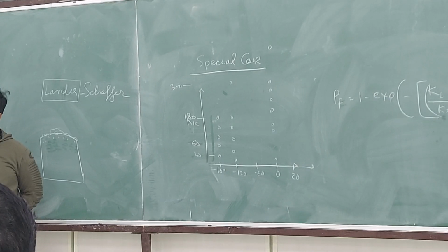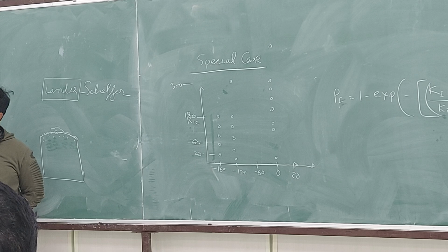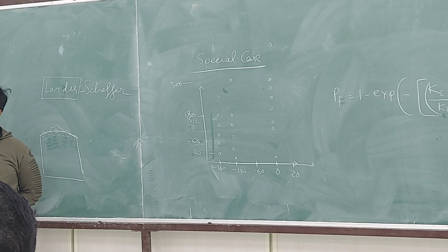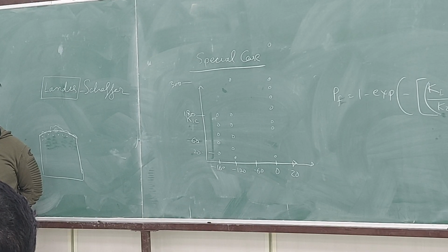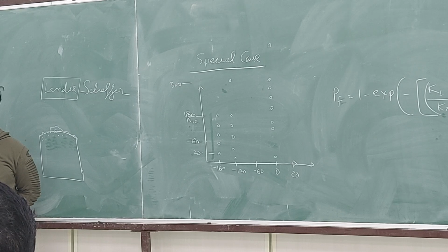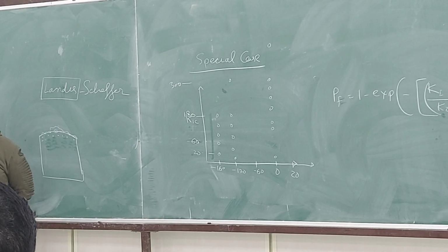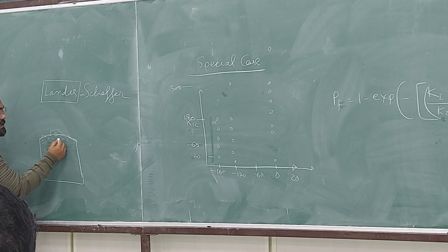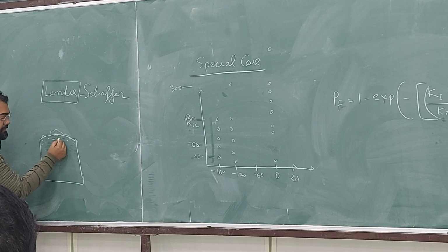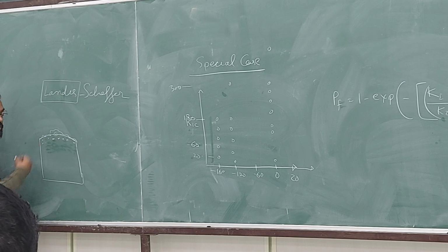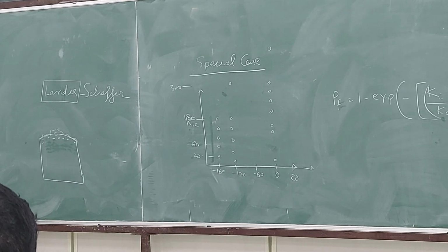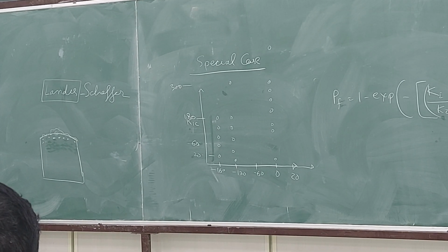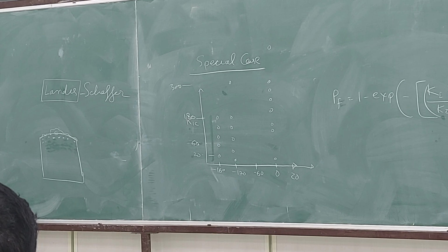If the material surrounding it could stretch, then it will become a void. If the matrix couldn't stretch much, then it will act as a very small crack, a micro crack. So all of these broken particles are stress raisers initially, and once they break, they become micro cracks. Not all of them, it depends on which temperature you are doing it at.